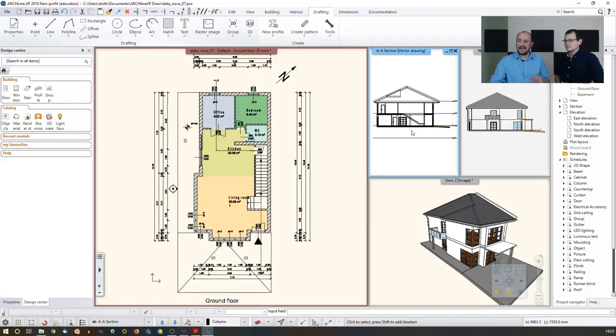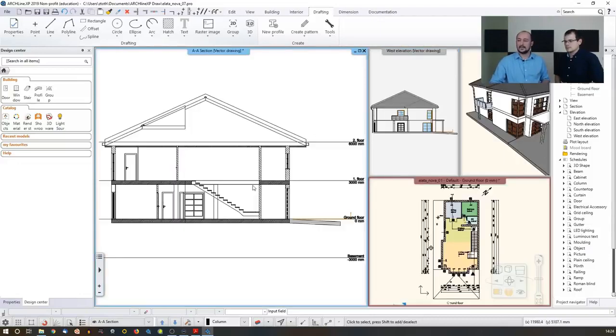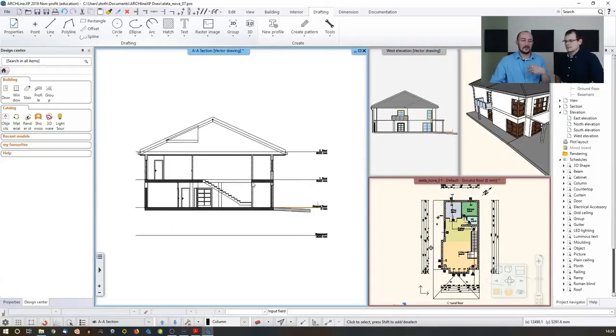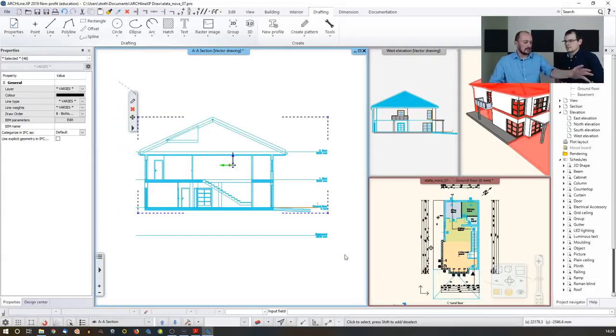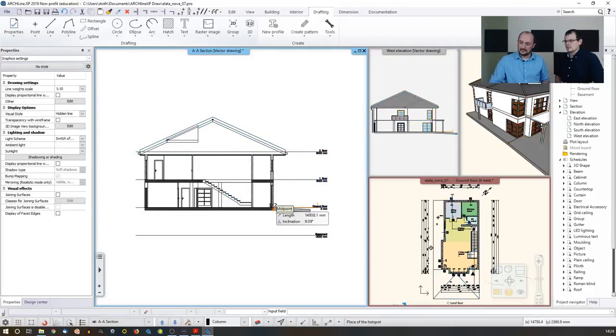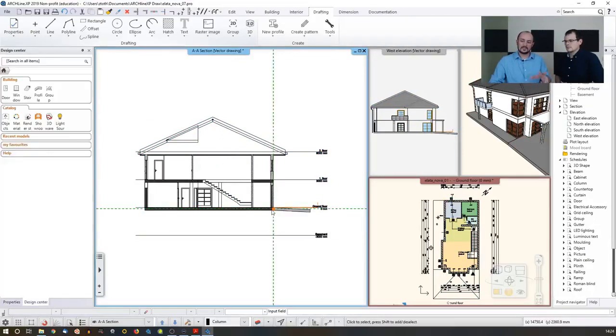So now we have a dynamic section drawing, which is still in connection with the 2D content. If I would like to make an unlinked copy of that, I just select the whole content and use Control C to copy, and let's pick up a reference point. This is the point which I grab this content with. So I just hit Escape. Now I've created a copy of this.